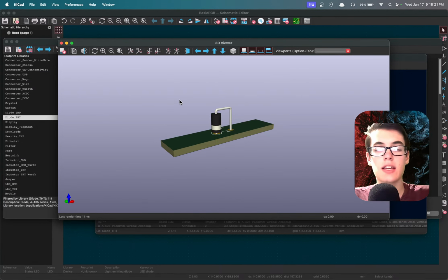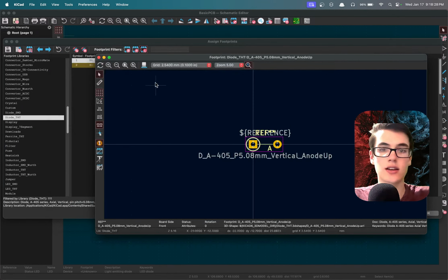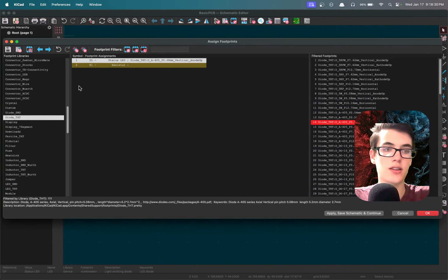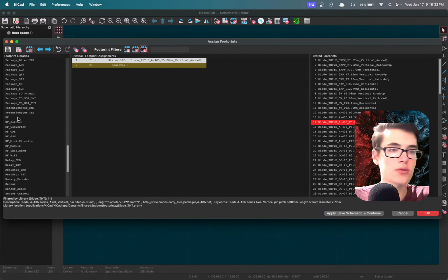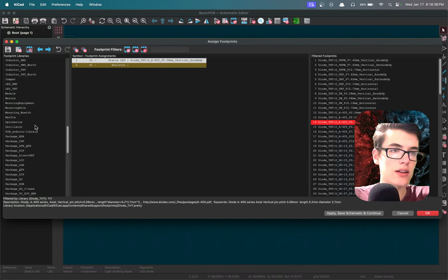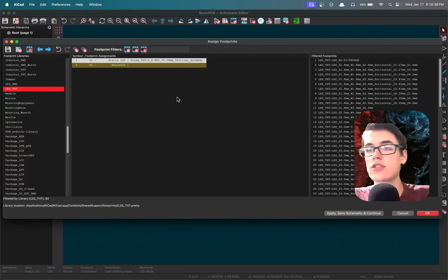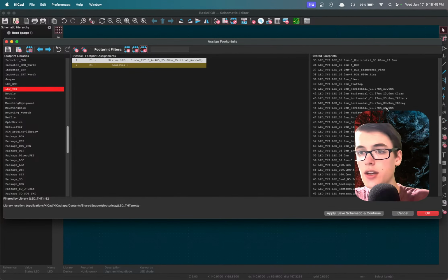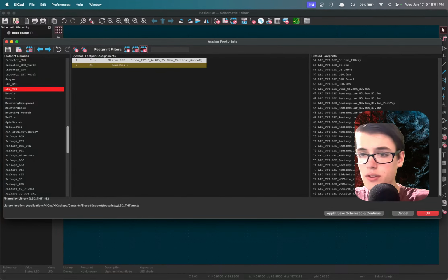Now, keep in mind, this is diodes here. I think I selected the wrong category because obviously this is a diode that does not emit light, and that is not what we want. So let's scan through and see if maybe there's an LEDs specifically category. Yes, LED THT. Okay, that's much better. They did separate out the LEDs that actually have light, and that's what we want. So let's look in here for a 5mm LED. That seems much more promising.